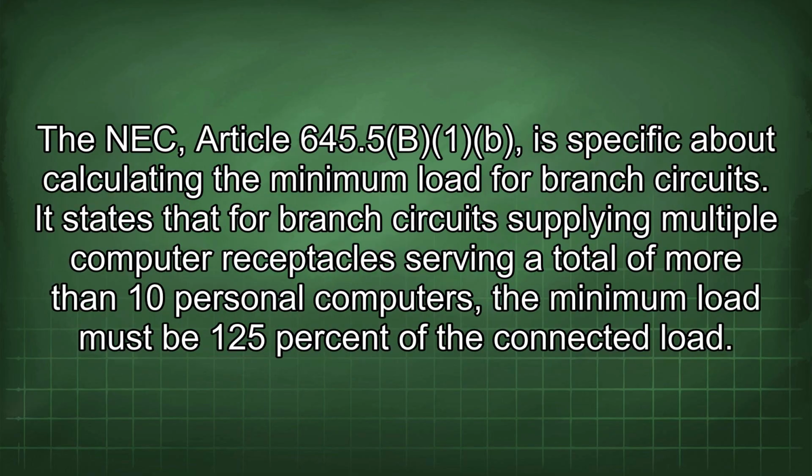The NEC Article 645.5 is specific about calculating the minimum load for branch circuits. It states that for branch circuits supplying multiple computer receptacles serving a total of more than 10 personal computers, the minimum load must be 125% of the connected load.